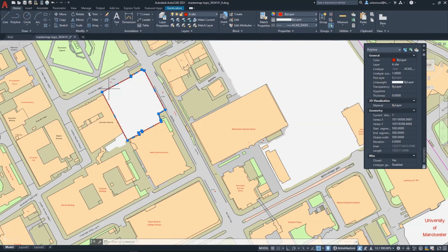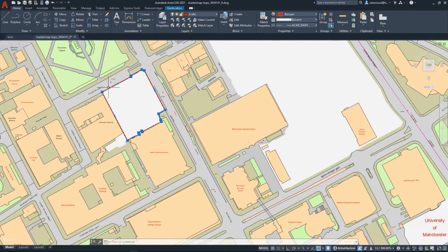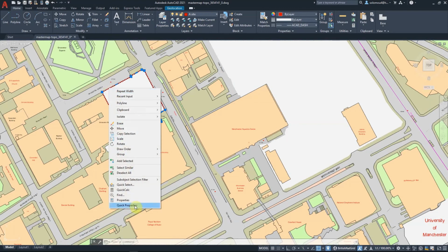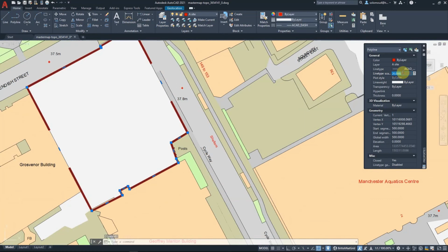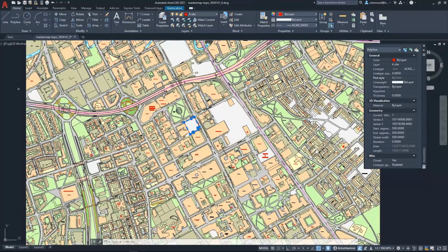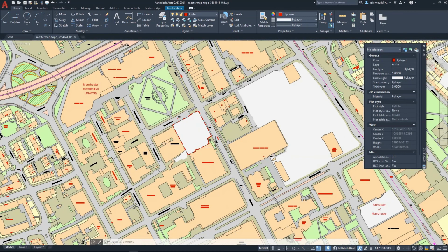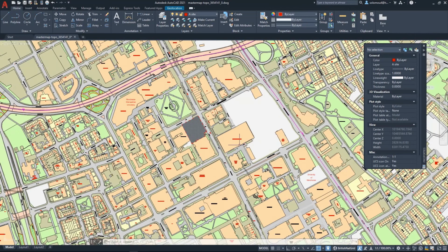I've got our properties open here, but if you right click and we go into properties and that thing pops up, there's a line type scaling here, which you can change. So if we scale it by 20, for example, see, that's too big, way too big. See the spacing there? I think the appropriate would probably be like 3, maybe even 4. There we go. So when we zoom out, we can still see spaces between them. Maybe if we zoom out that much, we need to be around about 6, so we can identify the areas more. Okay, perfect. So we have that.